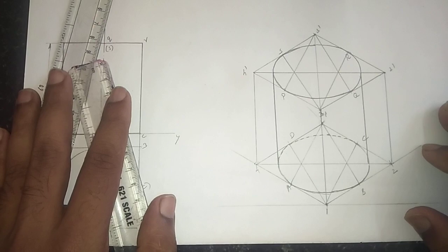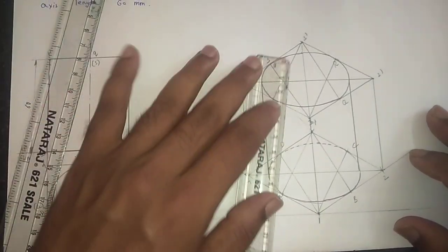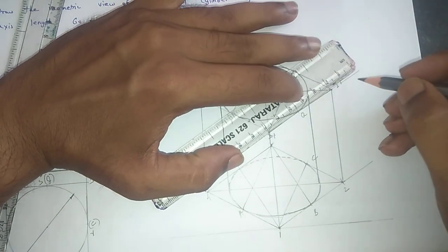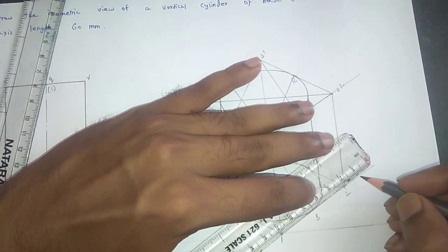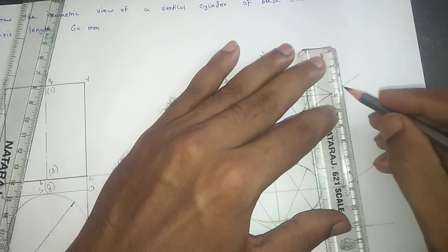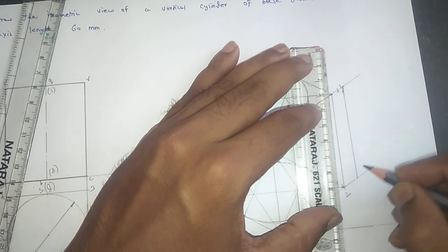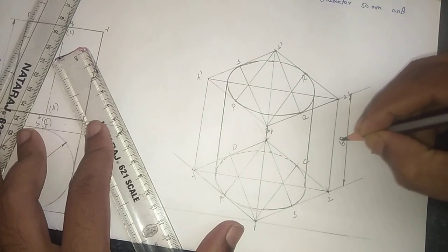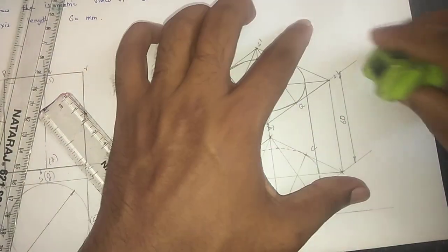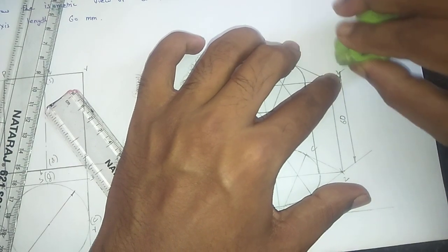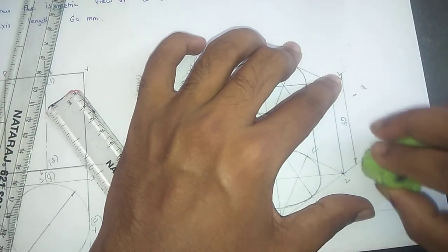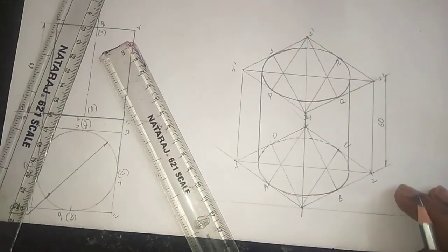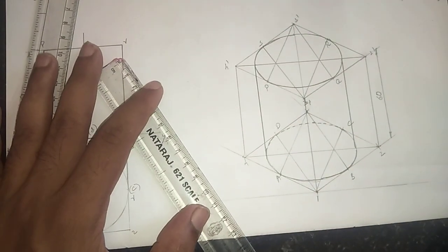So this is the 3D view, isometric view of the cylinder, and here also we need to mention the dimensioning of the object. So from here I draw one extension line and at 10 mm distance I draw the dimension line and put the arrowhead, and here we can mention the height of the cylinder. This value is 60, and from the arrowhead you leave 3 mm and remaining line you need to rub that, and in the bottom mention all dimensions are in mm, scale 1:1.